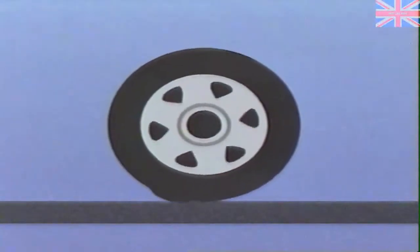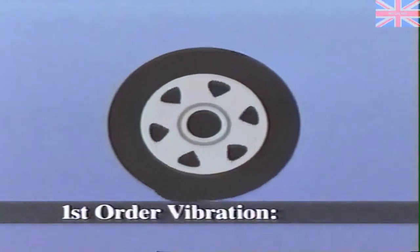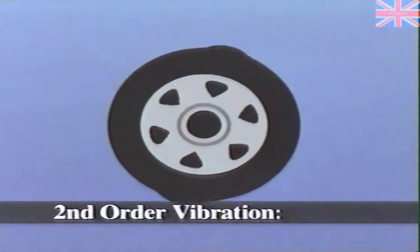Order refers to the number of disturbances created in one revolution of a component. For example, one high spot on a balanced wheel creates 1 disturbance per revolution. If the wheel rotates 10 times per second, the first order vibration is 10 hertz. Let's add another high spot, producing an additional disturbance per revolution. If the wheel is rotating 10 times per second, it now produces 2 vibrations per revolution, creating a second-order vibration